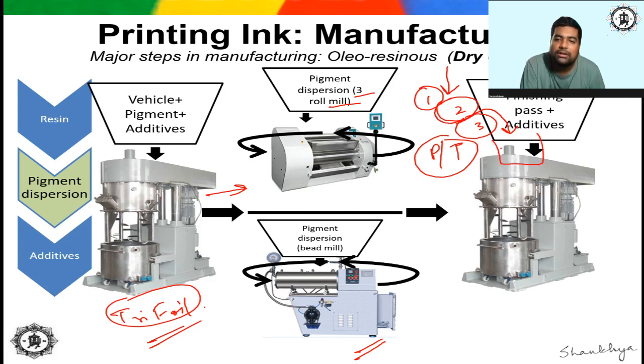There is a pot given on which the ink falls. The pressure and temperature to which the ink is exposed, along with the shearing forces that the rollers apply on the ink, cause the pigment particles to get uniformly dispersed within the vehicle. It also ensures that the pigment particles are broken down into smaller pieces and have a uniform coating of the vehicle around themselves. This will prevent coagulation and ensure that the pigment remains well dispersed throughout the vehicle, throughout the ink. This is one approach.